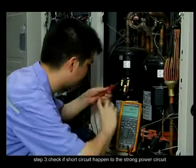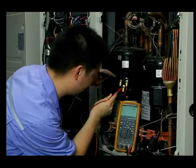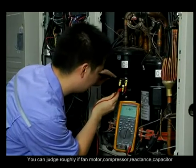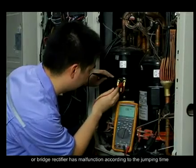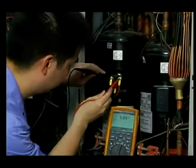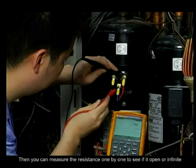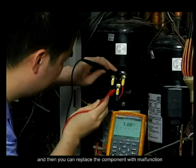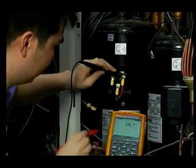Step 3. Check if a short circuit has happened in the strong power circuit. You can roughly judge if the fan motor, compressor, reactance, capacitor, or bridge rectifier has malfunctioned according to the jumping time. Then you can measure the resistance one by one to see if it is open or infinite, and then replace the malfunctioning component.